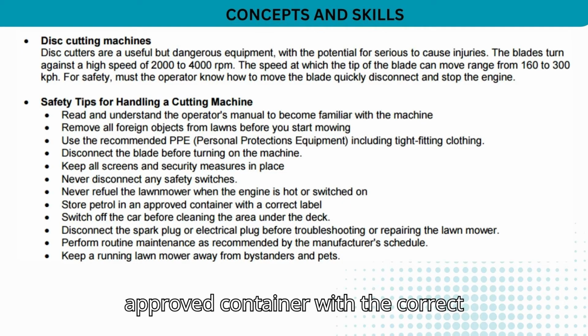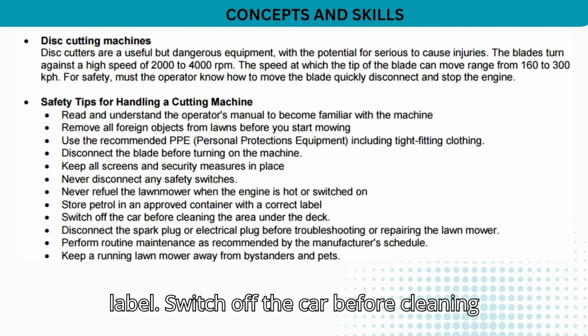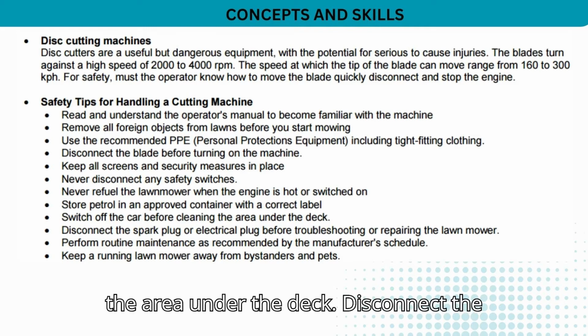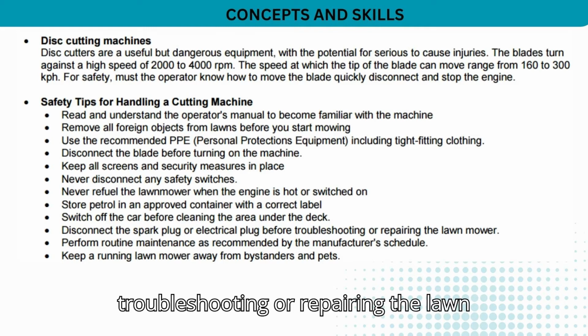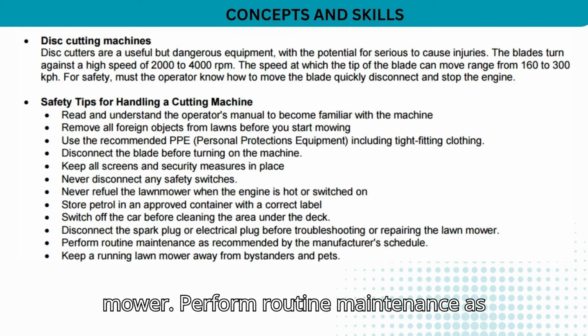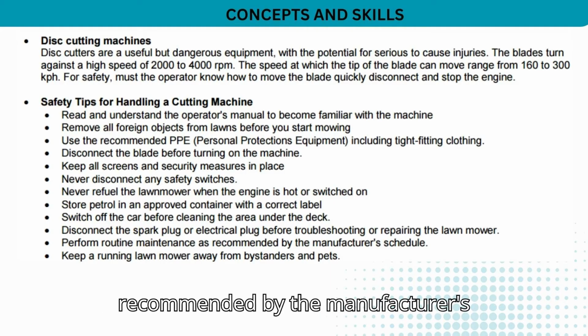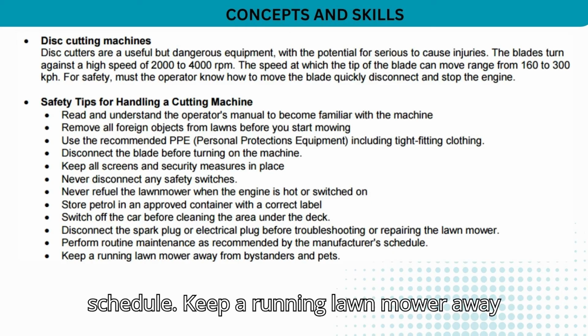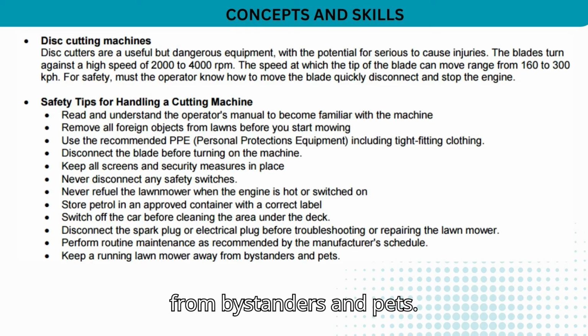Store petrol in an approved container with the correct label. Switch off the engine before cleaning the area under the deck. Disconnect the spark plug or electrical plug before troubleshooting or repairing the lawnmower. Perform routine maintenance as recommended by the manufacturer's schedule. Keep a running lawn mower away from bystanders and pets.